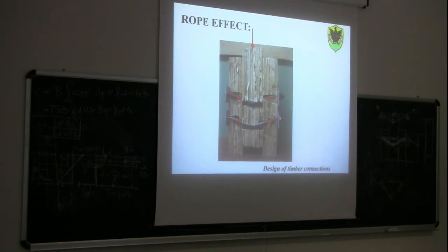Bearing. This compression force may plasticize the wood itself, but to avoid this, the washer must be quite big, not like the washers that we use for steel construction. Those washers here are 2 or 3 times larger to avoid bearing, to avoid this indentation of the wood. Now, what is the other effect on the total spacing of this compression force?